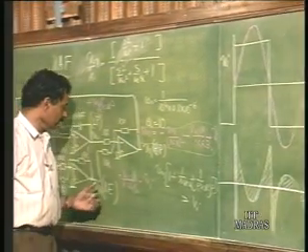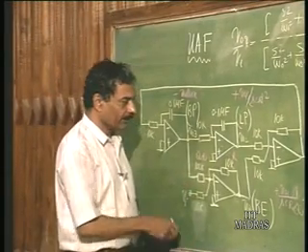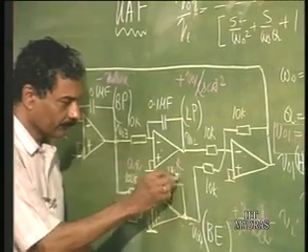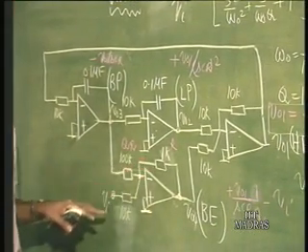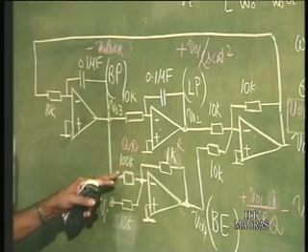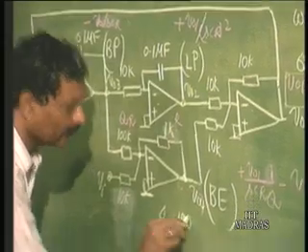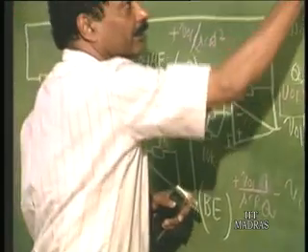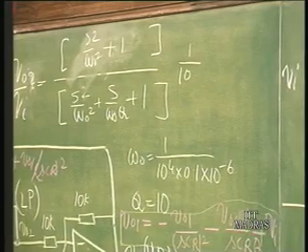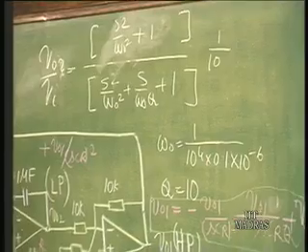This is a high Q circuit. I have purposely made this Q pretty high here. Instead of using 10K, if I use for example 1K here, this input is going to be also attenuated by 1 over 10 here, but Q is going to be 100. So, we have designed it for a Q of 100, and therefore here input attenuation is 1 over 10 instead of 1 in the earlier situation. This is going to be demonstrated by Devaki.